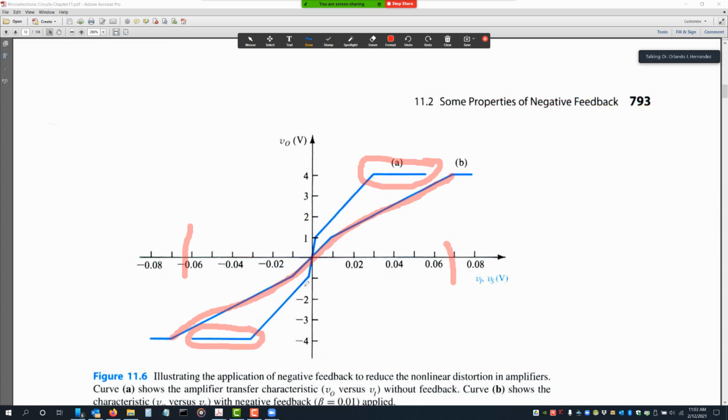And you have seen this with op-amps without feedback. They're used as comparators. Why? Because it has this nonlinear behavior. A comparator is a nonlinear device, and you actually take advantage of that high gain. And also, specifically in op-amps, the characteristic of the virtual short of the inputs is because of that behavior. Because it's saying that if you want your op-amp to operate linearly, which is where you want it to operate, then the input difference has to be very small.